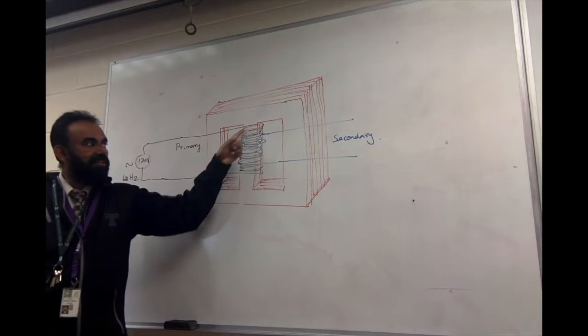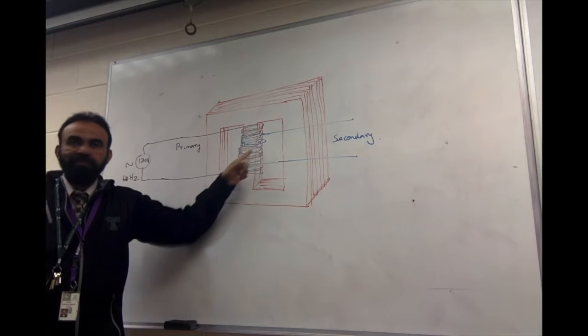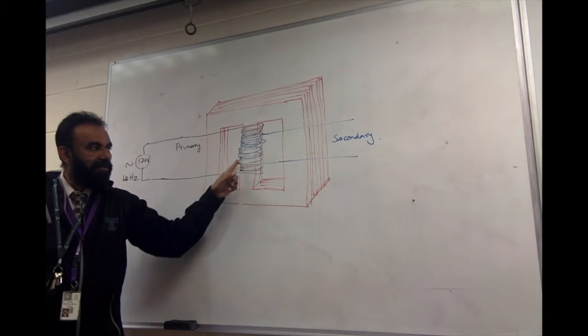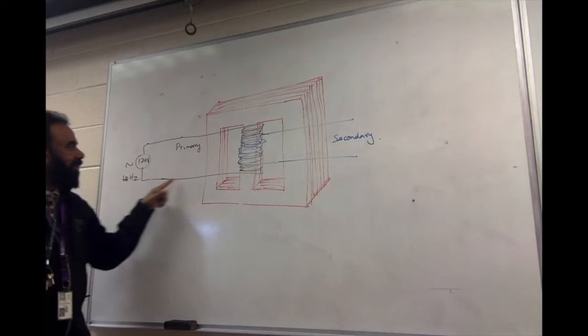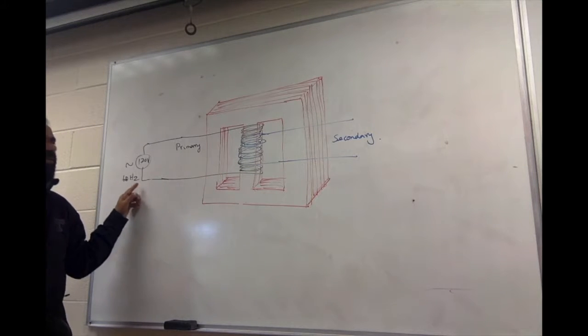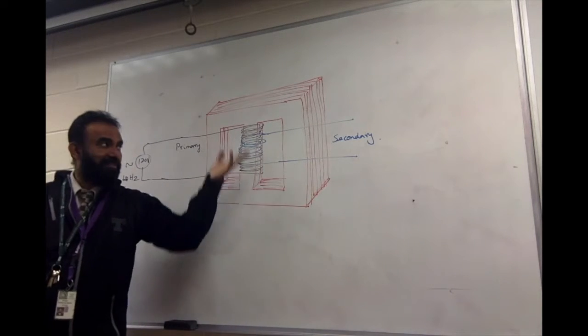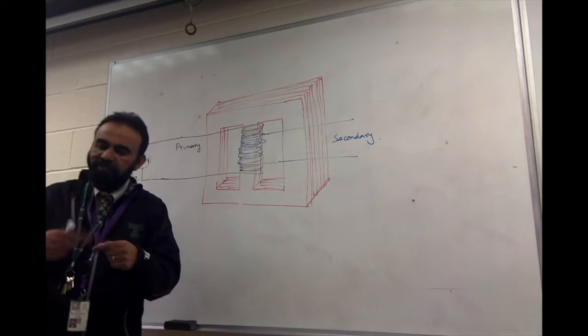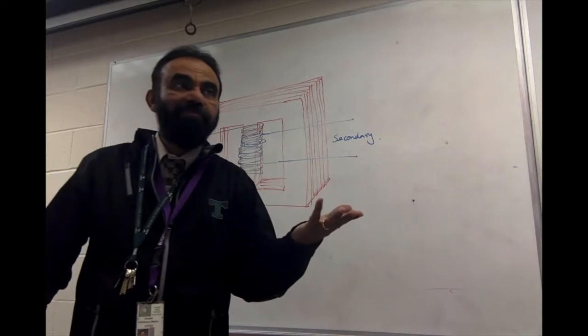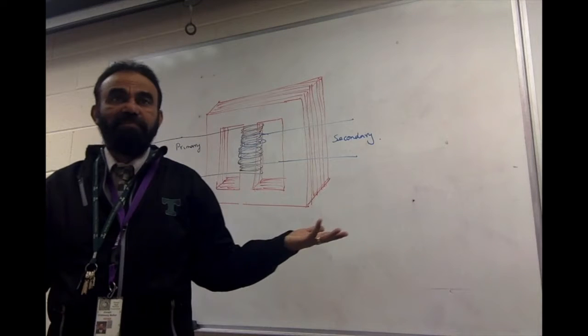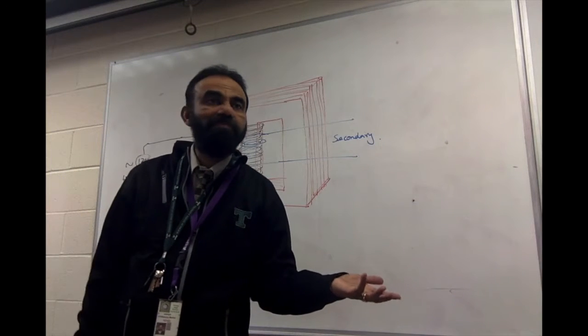That AC is connected to a copper wire. Think of this, all you see here is a copper wire, and the copper wire is back here. How much will be an approximate resistance for a copper wire? Even if you have a lot of turns, it's copper. So maximum 1 or 2 ohms, maximum, right?